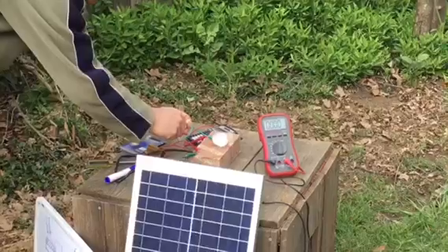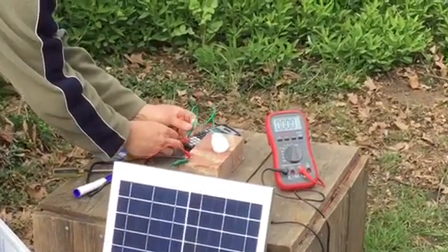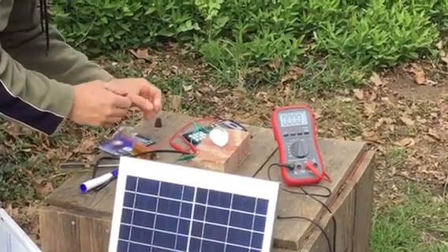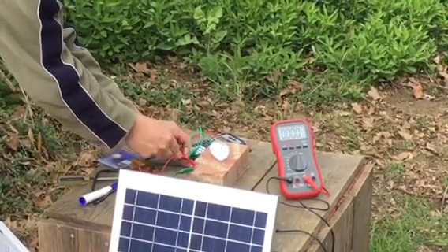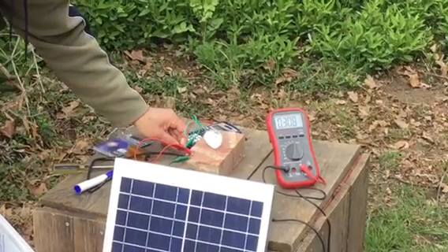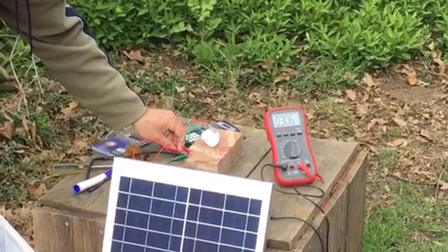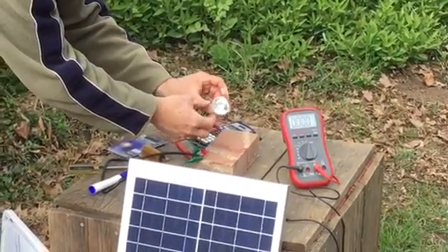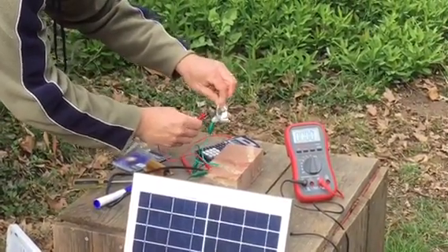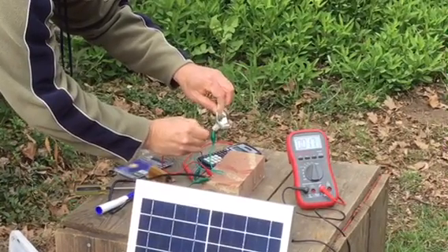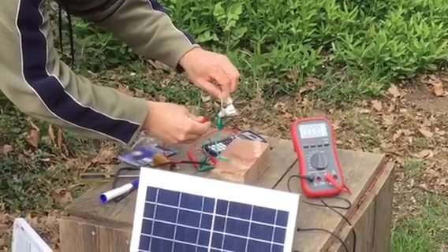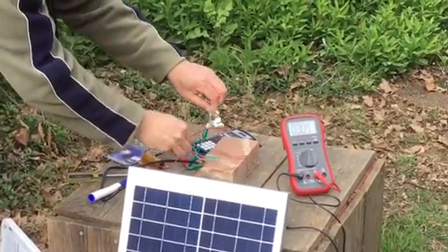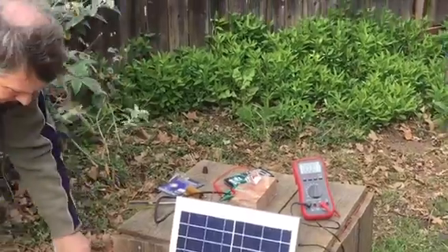Okay, and I'm going to try to hook it up to the PV panel. And I got all this wiring, which is just extra stuff. So first thing I'm going to do is try a short circuit, and let's see if we get any current. So about 0.3 amps. Okay, now I'm going to try to go through the light bulb. Try not to cut myself. Unfortunately, this got shattered, but that's okay. Hopefully you saw that you got about the same amperage. So once again, a different resistance and you end up getting the same amperage.